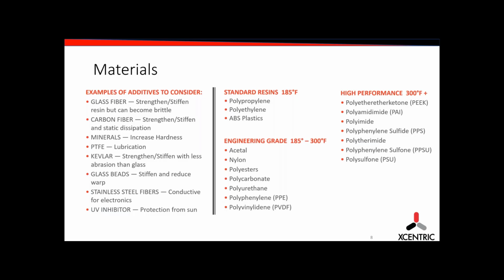Yep, and there's a lot of materials out there that come preloaded. There's a lot of glass fiber options available. Glass and mineral are probably the two most common, and you're going to see it mostly in nylons: 10%, 30%, 50% glass filled versions of it. But yeah, these can be formulated separately or together, or they can be bought off the shelf with most of these additives already in them.